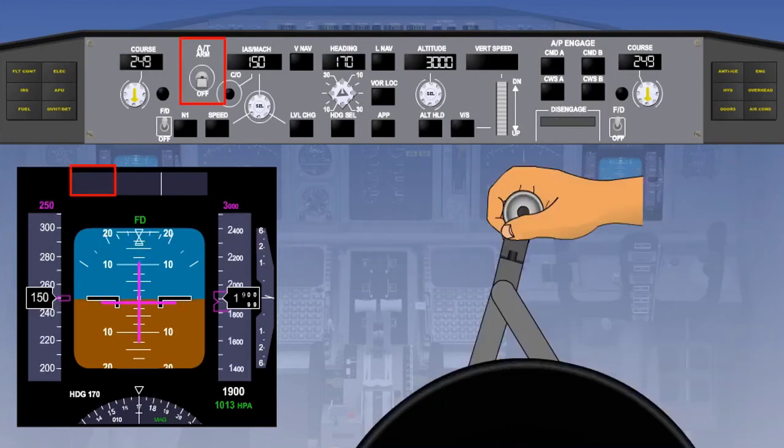With the auto throttle arm switch at arm, the auto throttle go-around mode is armed when descending below 2000 feet radio altitude, with or without the automatic flight director system engaged. Once armed, the auto throttle go-around mode can be engaged until 2 seconds have elapsed after landing touchdown.